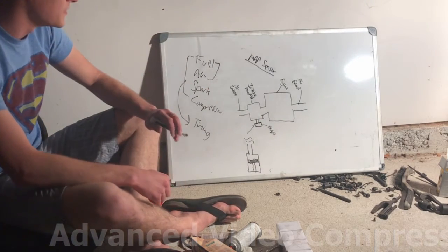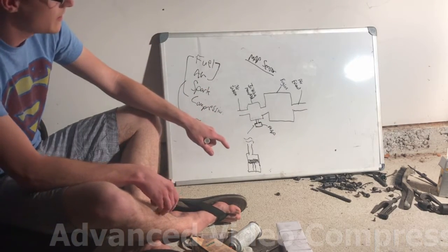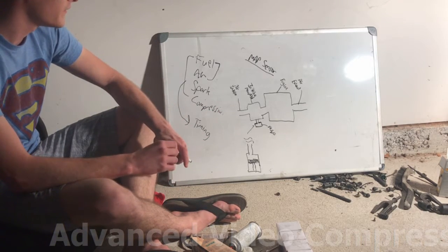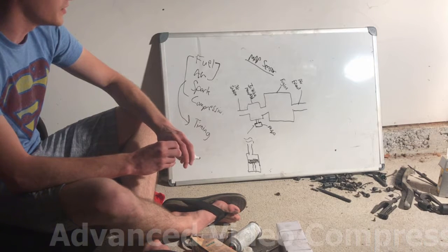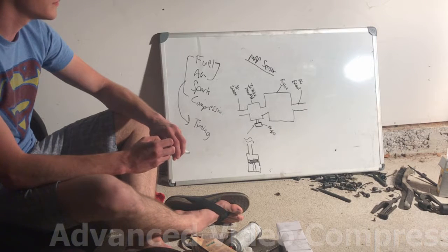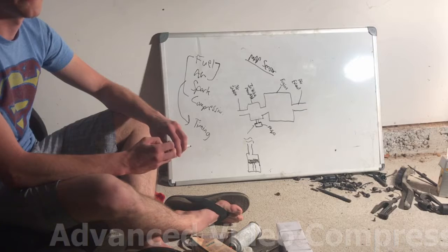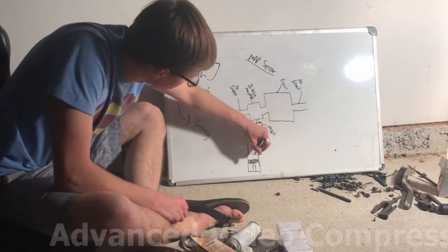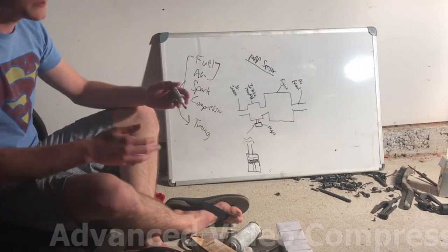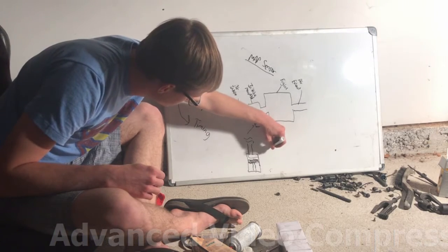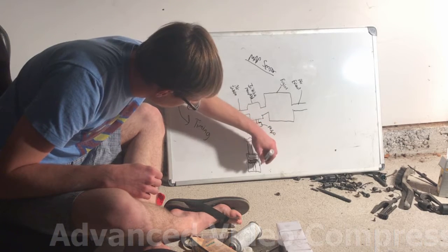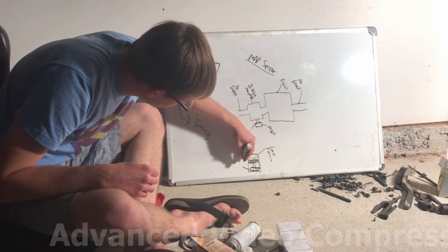Based off the position of this diaphragm inside this housing, the MAP sensor is going to output something called a voltage to the car's computer that is going to tell it how much pressure is in the intake manifold. So let's say this plunger is all the way at the bottom. Let's say it's here. My pressure is obviously going to be lower, so this would be lower pressure than if it were at the top, producing a state of higher pressure.